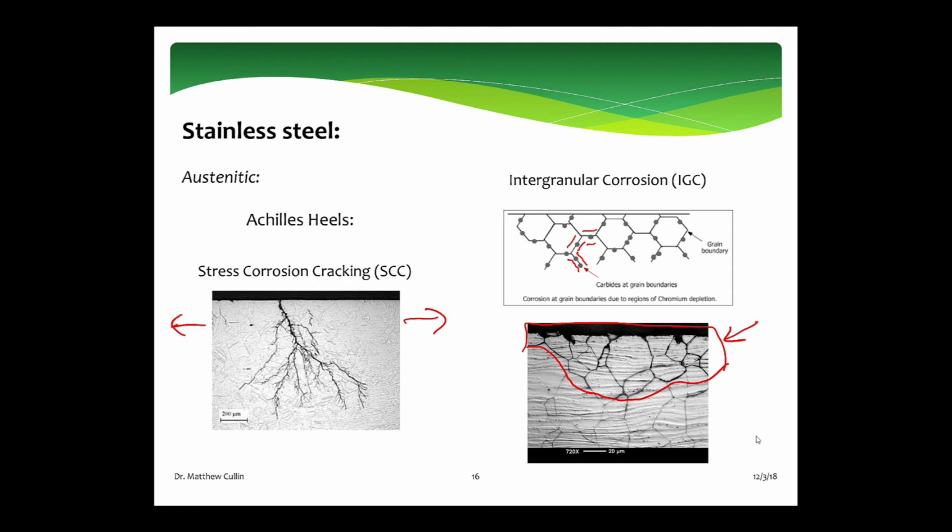So when you're welding stainless steels, particularly austenitic stainless steels, you have to be very careful in how you weld them and how long you spend at a particular temperature, because you don't want to let these chrome carbides form. Or if you weld them in such a way that they do form, you need to know about it so that you can take that weld and, after the fact, heat it up, dissolve out the chrome carbides, and then come through the temperature danger zone very quickly so that they can't reform.